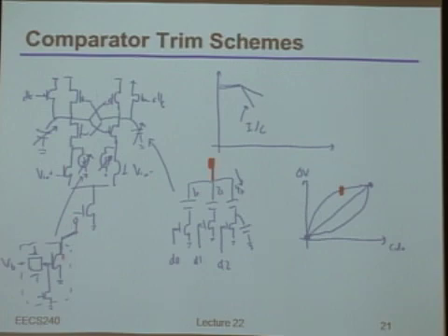Now, by the way, just in case you thought I was being nice, when you build, for example, these DACs, you better keep in mind that there's offsets in those transistors too. Okay, so when you build the DAC, you actually have to build a DAC that really will get the step size you claim you're getting. So again, user beware, because there is some additional sizing and design procedure you'll have to apply to get the DACs to actually behave the way you want them to. And that's not just because I'm trying to be mean, it's to make sure you actually understand why this could happen, because otherwise if there's an offset, you just make all these things as small as you can, and you might get an unrealistic result.